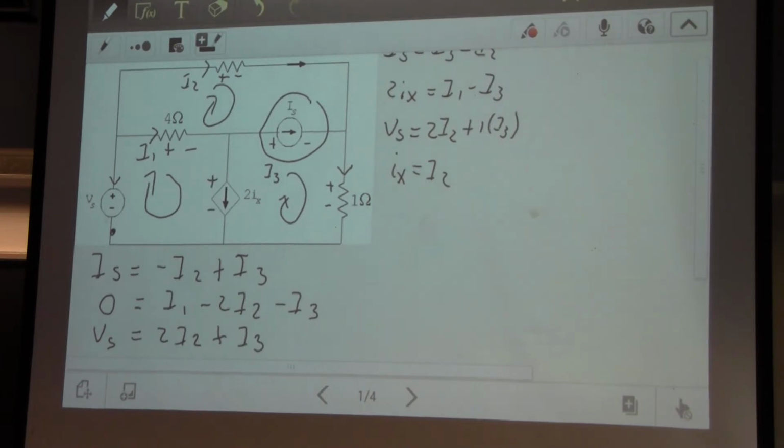So those are the 3 equations, and all I did was rearrange the terms so that all the loop currents are on one side, and I got rid of Ix. So I have a system, the 3 loop currents are there, and I can solve for this, right? You probably already know that this is a linear system, right? Here we have I1, I2, and I3, just as linear terms. They just have coefficients and they're being added or subtracted.